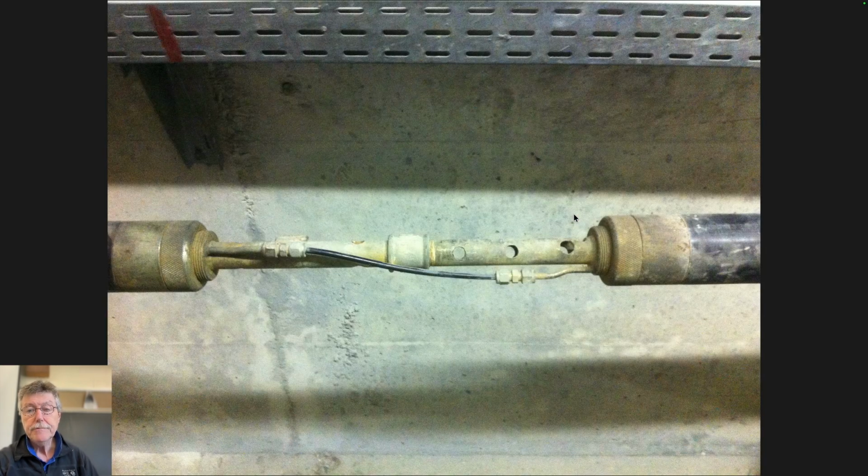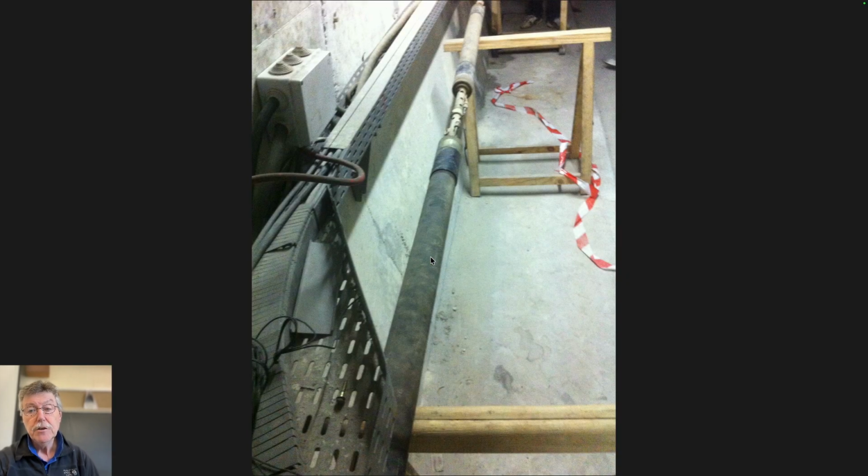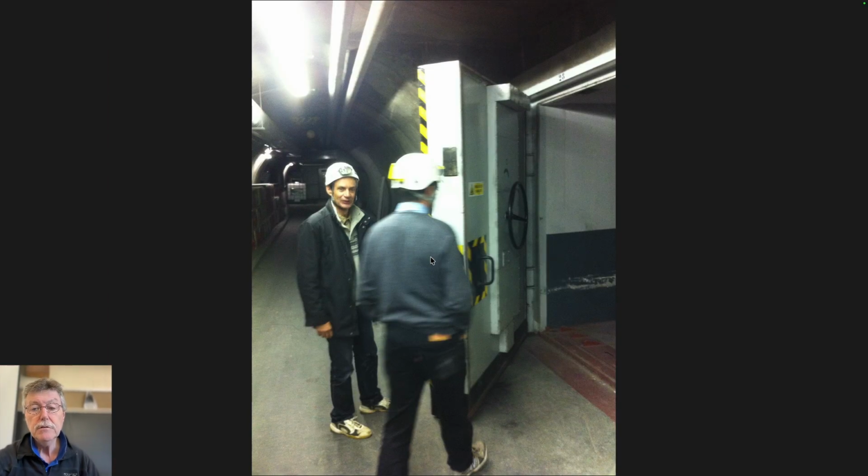So this is a straddle packer. On the right-hand side of the packer, left-hand side of the packer, a choice of the height, length of the zone. This is water introduced along the axis inside this straddle packer to be able to run a slug test, Lugeon test. This is the nitrogen supply to inflate the lower packer. These are probably 4 inches in diameter. This is probably 18 inches separation. You can change the separation of the straddle if you want to sample a bigger zone.